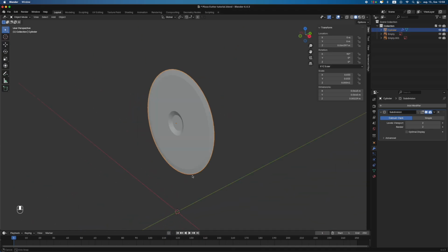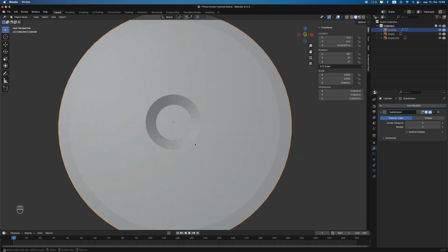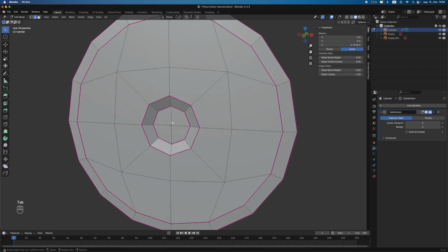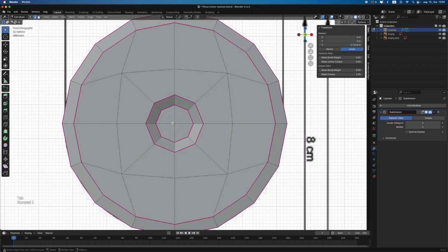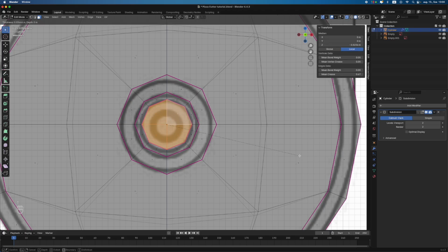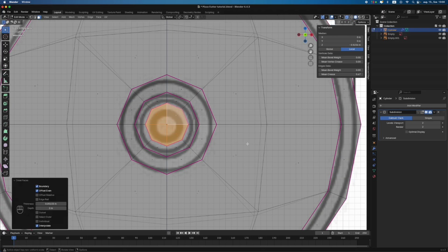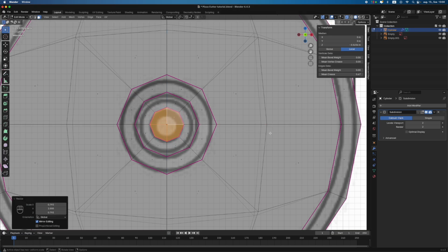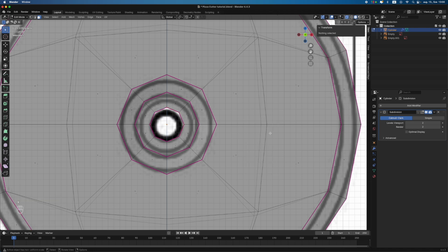Now as you can see, the blade is almost ready, or we can call it ready, but I want to make a hole in the center so the screw can grow in. We can do it by pressing to edit mode, pressing 1 on the keyboard, Alt Z to go to X-ray mode, and select these faces, inset them again, and I want to make it kind of this big, and I want to delete these faces.